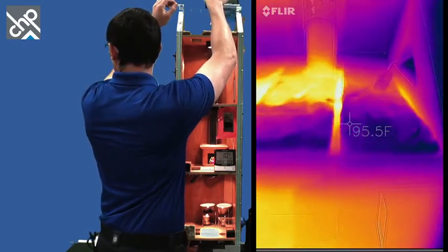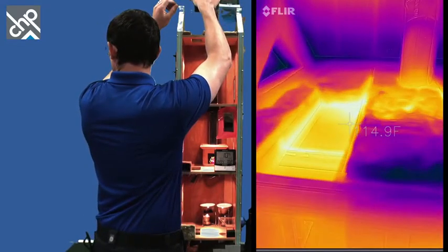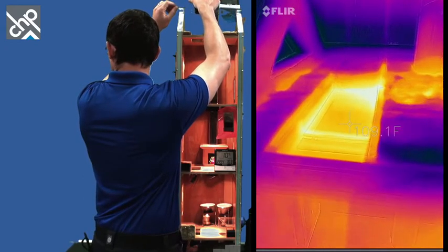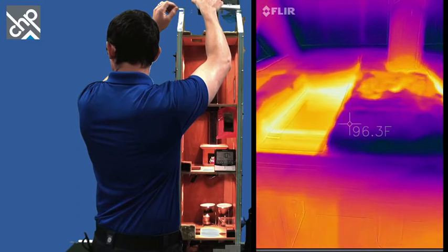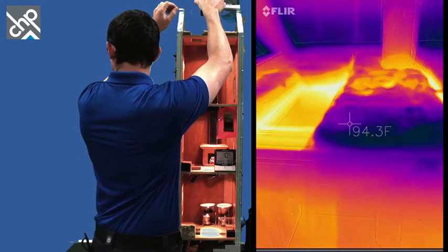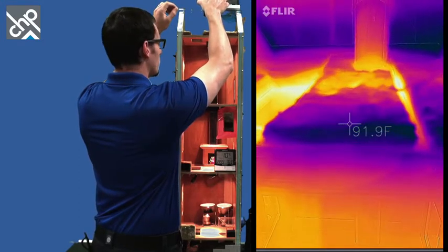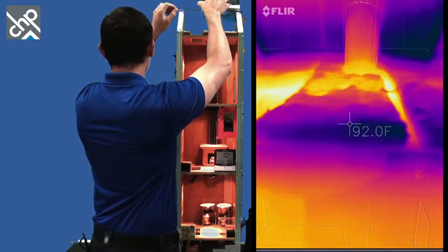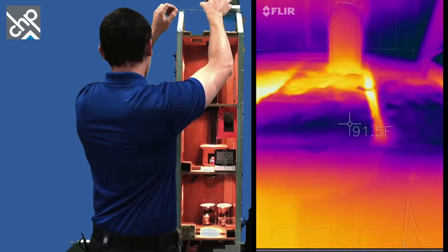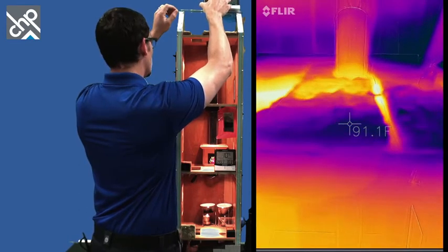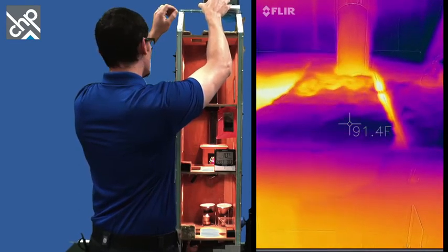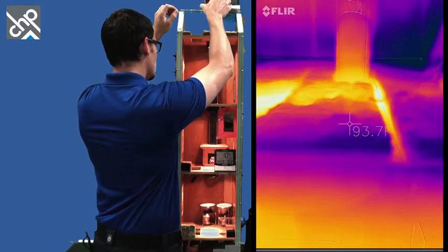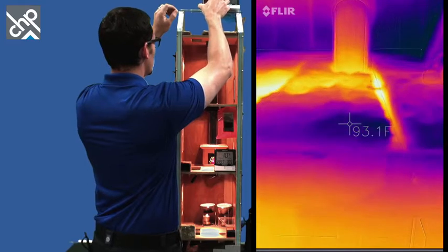It doesn't do very well with reflective surfaces. So if you guys can see, here's my attic hatch, and if I pan across here, I can see some cool insulation. I can also see the hot spots for my framing members in the attic. My ceiling joists are showing up as hot spots because it's hotter in the house than it is in the attic. So there you can see that insulation is doing its job in the places it actually is in contact with the air barrier.